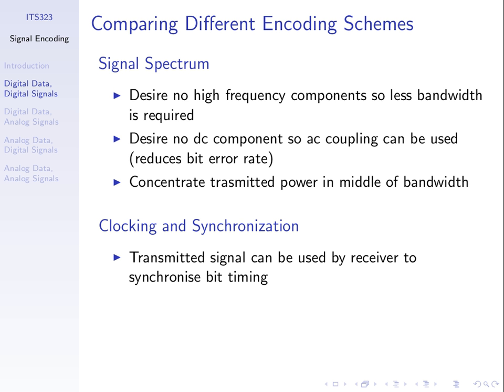And if we have a third pulse here and a fourth one, this is at 2.4, so the receiver thinks 1 millisecond, this is 1 millisecond, but in fact in real time it's only 0.8 milliseconds because its clock is wrong. So each pulse in real time would be 0.8, 0.8, 0.8, 3.2.